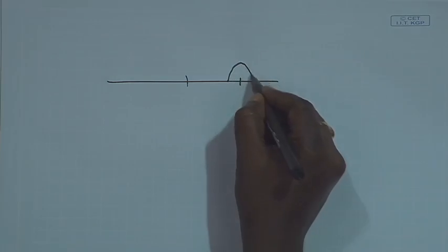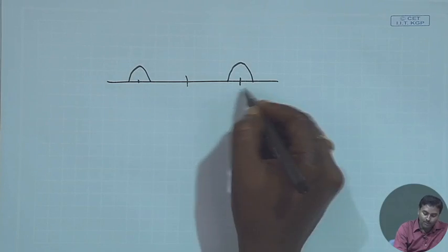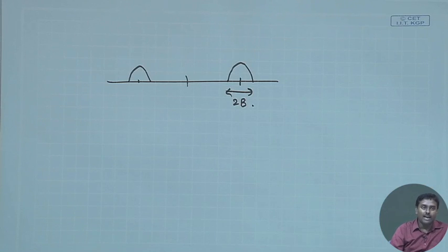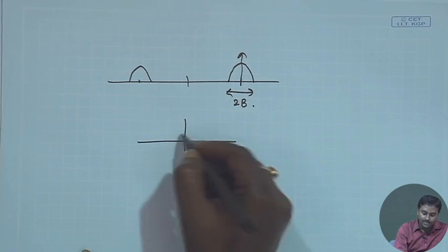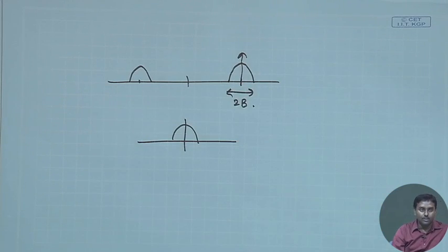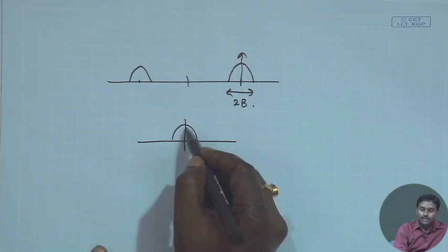Okay. So, in the last class we have already discussed the advantages and disadvantages of AM and DSB-SC. But in both AM and DSB-SC, if you see how it occupies the spectrum, with a suppressed carrier it occupies this entire 2B band. If I put the carrier on top of this, nothing else changes, at least in the frequency domain, it still occupies 2B. But I can see already, the message signal which is getting translated over here and creating this 2B band is even symmetric, right.